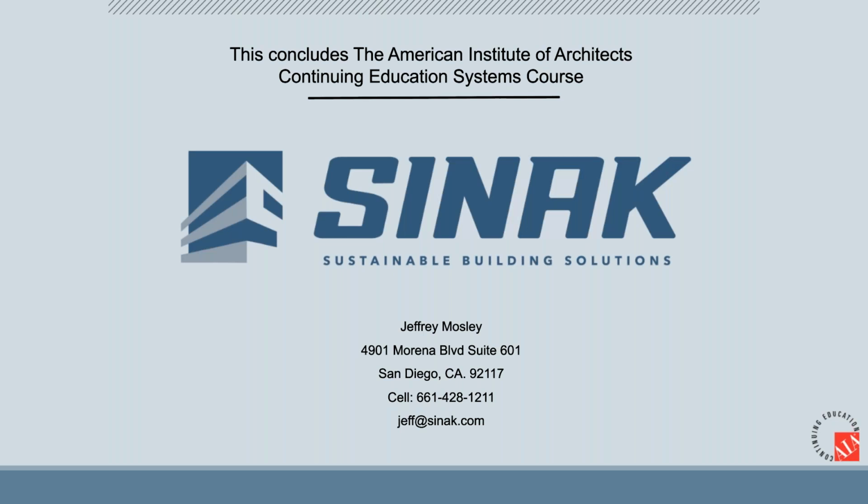The second thing, all Sinak curing products are developed based on function. There's an exterior product for curing called Lithium Cure 1000. That is designed for exterior colored concrete and air entrained concrete. Lithium Cure 2000 is designed for interior hard burnished steel trowel finishes. VC5 is our vapor control line that comes with a 20-year warranty, and WCE is our potable water line for like water treatment facilities. Each of those are permanent. They are applied the day of application. They permanently impregnate the concrete with a lithium quartz matrix that is inorganic, non-soluble, will not degrade, will not wear off, will not go away. So it both extends the curing curve well beyond 30 days, but it also controls the rate of drying permanently so that you get the best results.